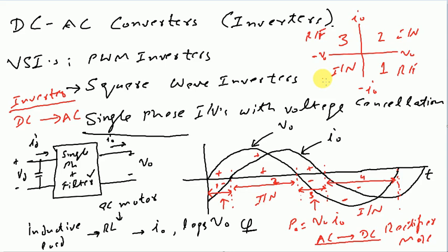Just as we had a case in which we discussed a rectifier circuit which could also operate in the inverter mode, we had mentioned that the switches over here should have the capability of allowing the current flow in the other direction. Or simply, we had described that this inverter should have the capability to operate in all four quadrants of the IV plane, that is this VI or IV plane. And this device should have the capability to operate in these four quadrants.